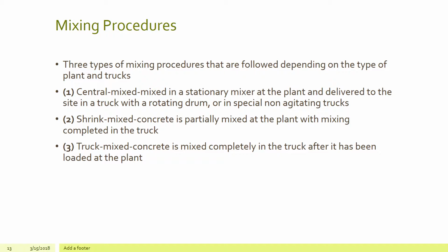And one of the key things here is once this concrete is in the drum and it's traveling down a road, there's a time frame that we have to actually get that out of the drum and have that poured at the site. If we don't, the concrete will start to harden inside the truck and we get what's called a hot load. If that concrete solidifies inside the truck, we're basically in there with a jackhammer trying to get it all out so that we can then use that truck again.